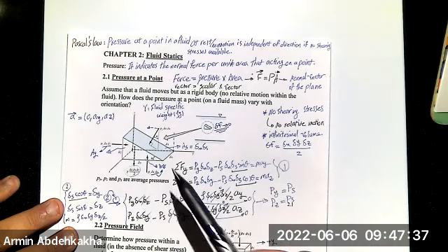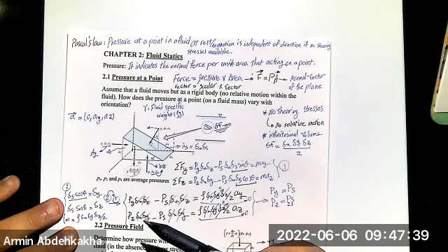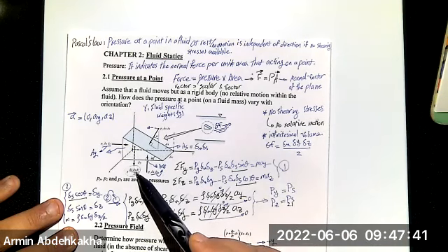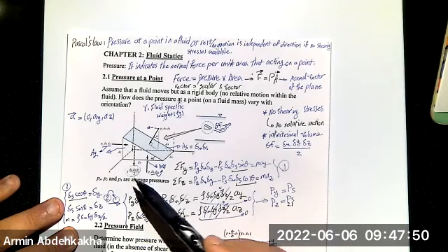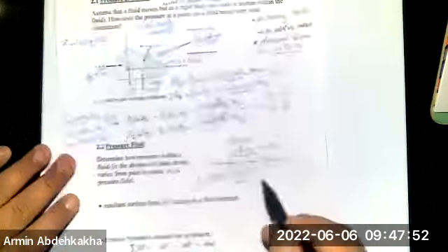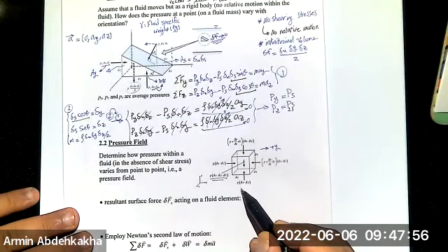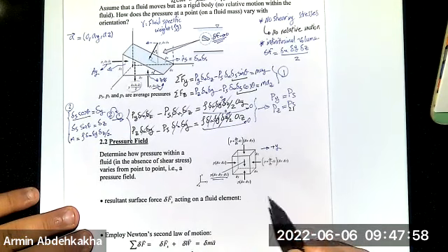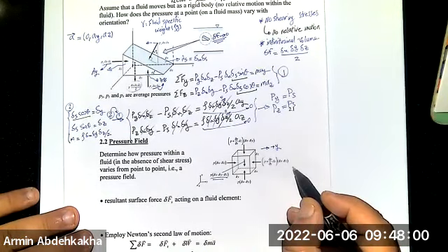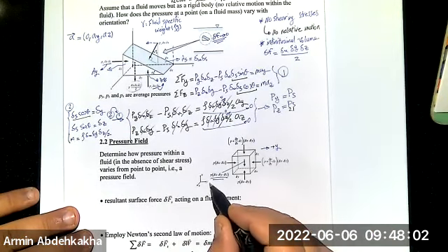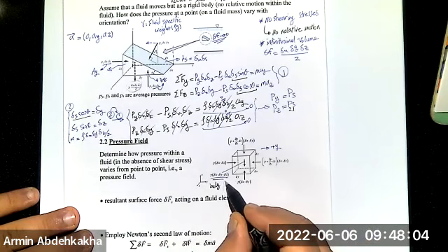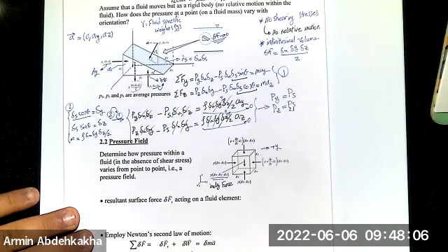That's why the pressures are independent of the size. But now we have to consider it, because you cannot just say that the volume doesn't matter and there is no body force here. So we need to use it and prove the pressure distribution, or pressure field. So this is the body force, and now we are going to consider that.